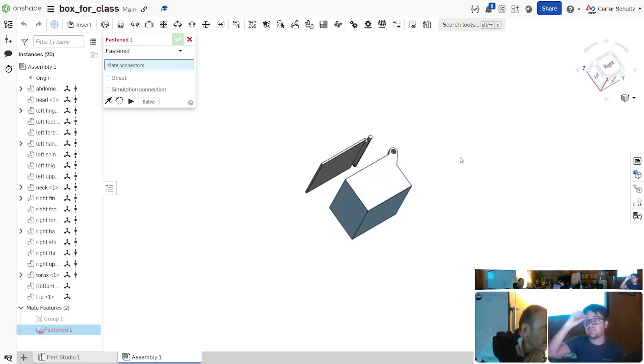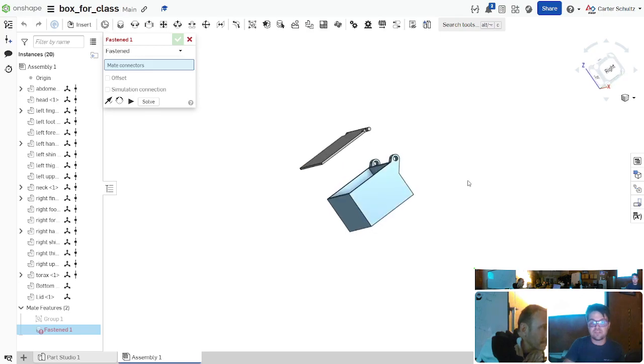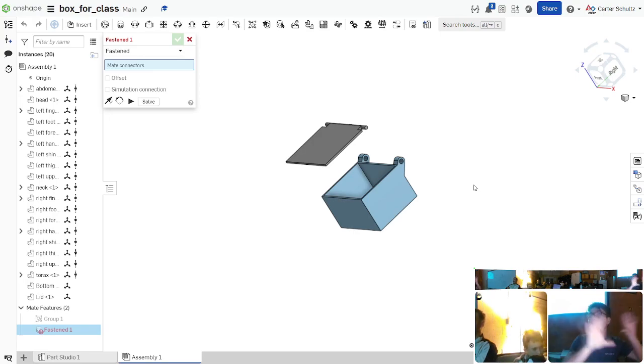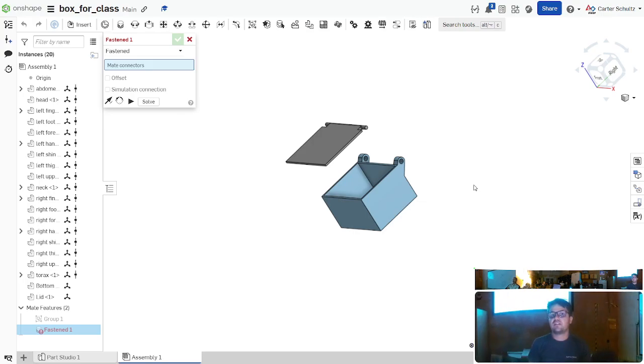So that part is logically separate from the bottom of the box, right? Yes. How does it work with the sketch? Because your sketch is still positioned with the box, I assume, right? Yes. The sketch creates two parts. The positions of those parts disappear when those parts are pulled into assemblies, and if I move them around in the sketch, those positions don't matter anymore. I got it. So you would back up in your timeline and change something. Yep. And when you did that, those are still mated, and it would just apply whatever changes happen.